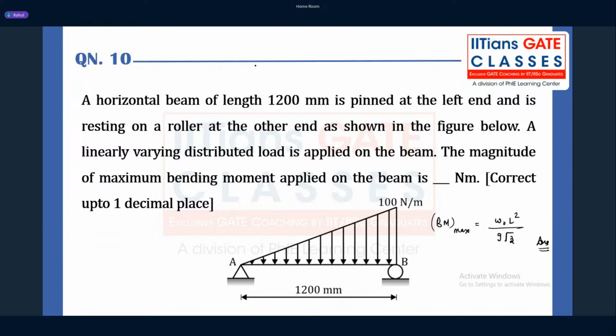Just like you remember the case for a simply supported beam under a uniformly distributed load, W naught L square over 8, that is the maximum bending moment. Like that, you try to remember these standard case results.